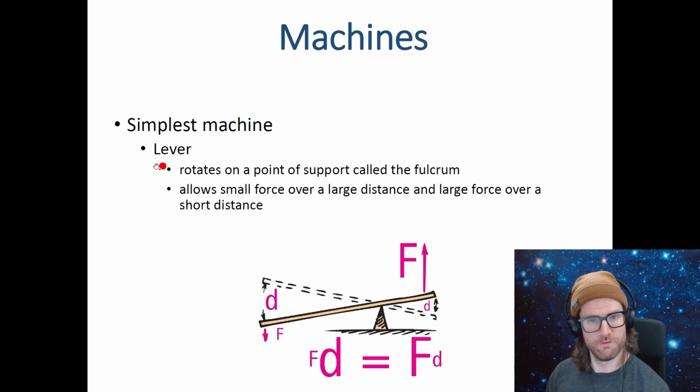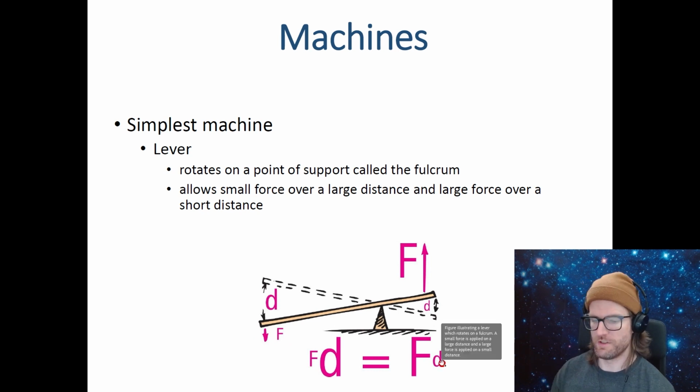So here's a lever. On this side, this lever moves a longer distance than this side. And so if we wanted to use mechanical advantage here, we can push this a long distance with a small force to move this a short distance with a large force. So if we put a heavy object over here, we can lift it with this large force, by moving this end a large distance with a small force. So that's small force times large distance equals large force times small distance. We can use this to lift heavy things.